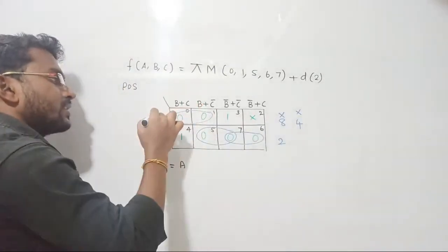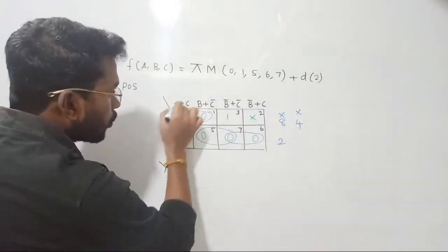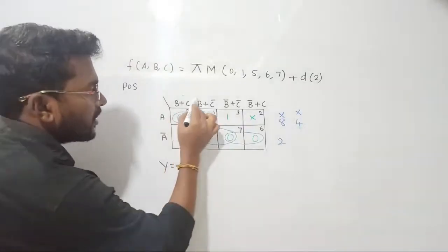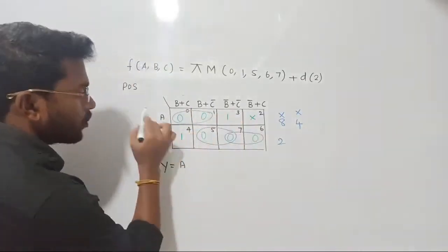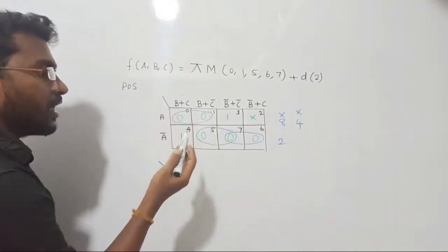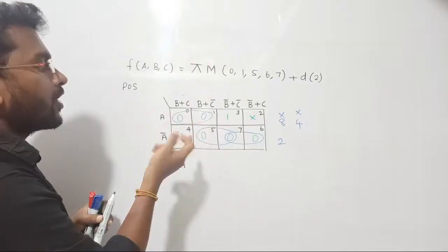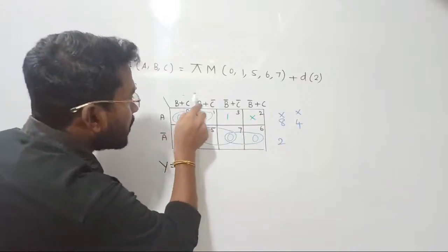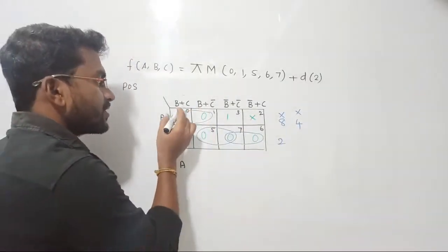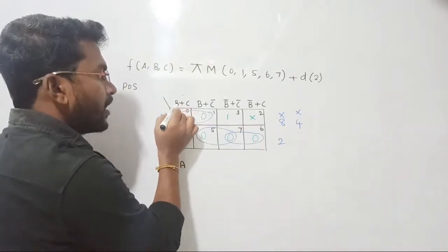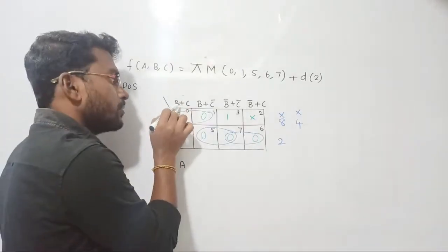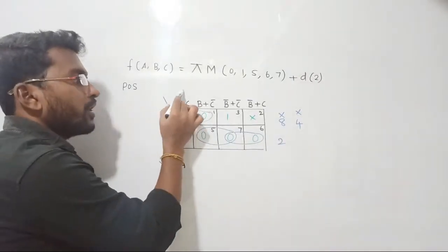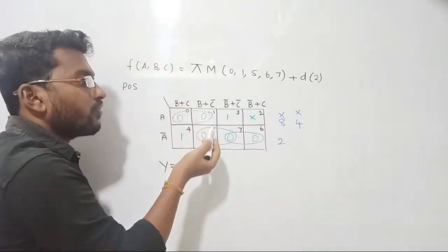Similarly, in the cross, first we have to perform OR operation, right? In order to group them together, these three literals are always grouped together, such that we have to use addition, because a, b, c are all grouped together. So in max term format, how do we write? a plus b plus c, a plus b plus c bar, like that. So we have to use addition, but in between these two we have to use multiplication. Why? Because this is a max term, in which we have already performed OR operation, so between the consecutive terms we should perform AND operation.